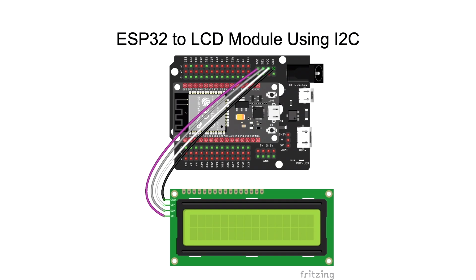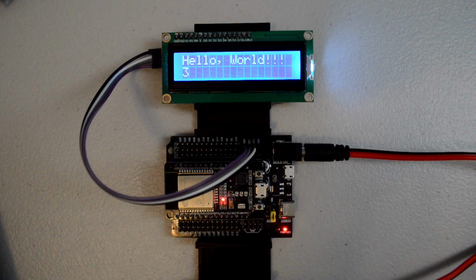Last of all, here's a diagram showing an I2C 1602 wired to an ESP32. Once again, we've simplified our circuit at a high level since we're just using 4 wires here. Here's an I2C 1602 wired to an ESP32. The breakout board obviously has been designed to take into account the I2C bus, since we've got the 4 required wires separated out into a specific unit on the breakout board. We have ground, VCC, D21, and D22 all together. D21 is the data wire, and D22 is the clock wire.